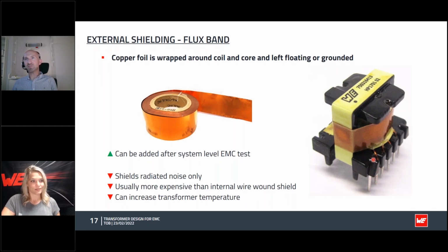So that provides us with pins so we can attach the copper wires, and then we can wrap the wires around this structure internally. Then we do layers of wire and then some tape and layers of wire on the secondary, and so we have a structure that we can automate for winding.